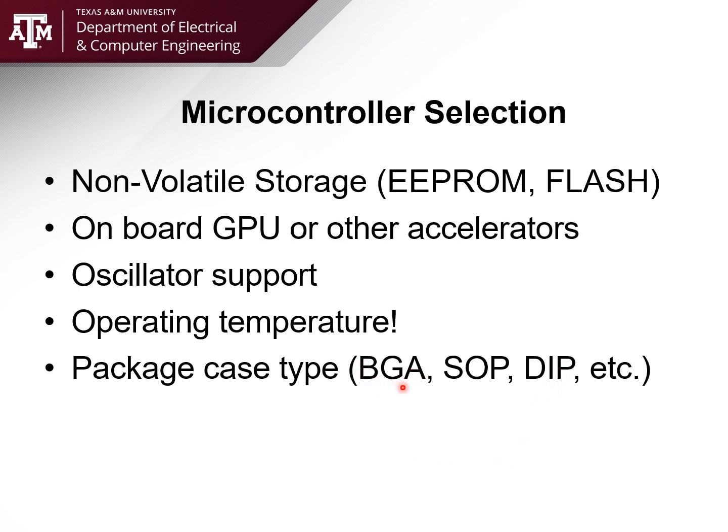Ball grid array, BGA, is not something you hand solder. It is done at the professional level, done in the assembly shop. Don't be one of these students who end up choosing a BGA package for their senior design project and wonder why we can't do anything with it. You're not going to be able to solder this on the board.